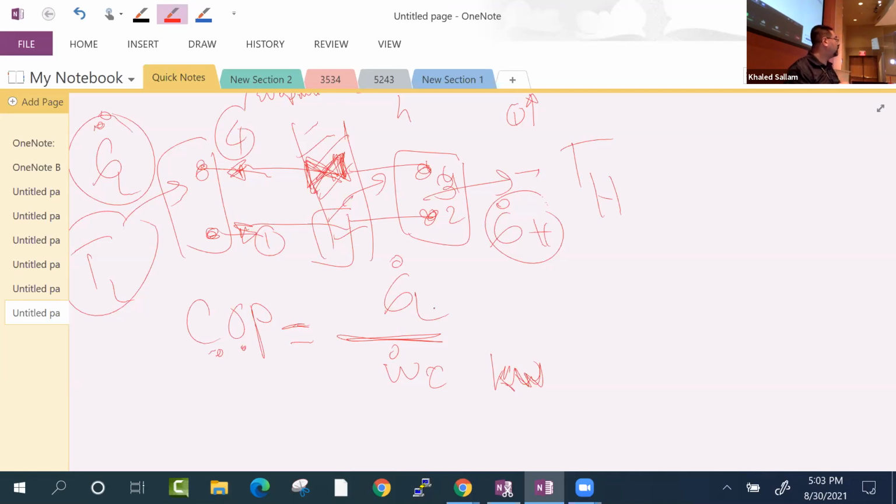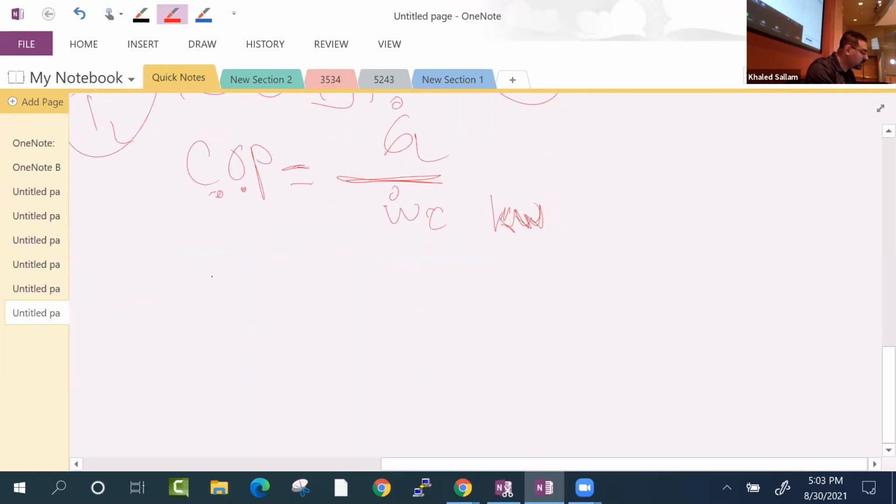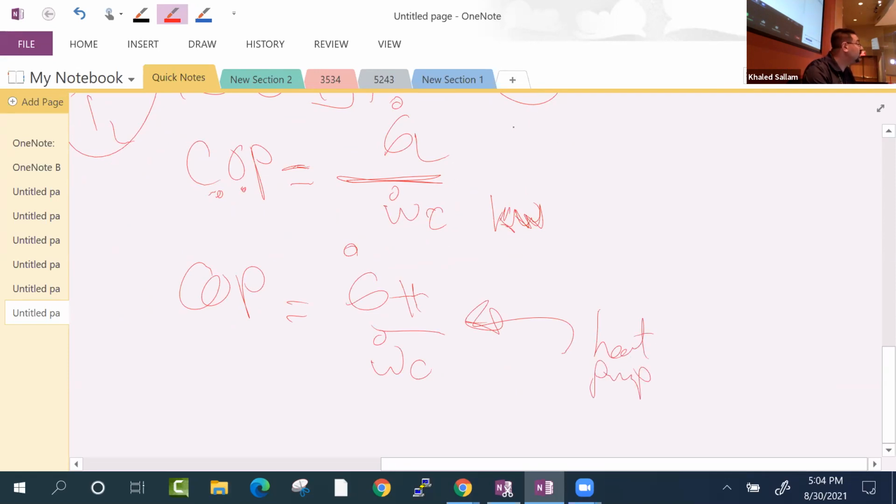So in that scenario, what do you care about? The Q dot H or Q dot L? Q dot H, that is your goal. So there is a COP that is Q dot H over work done by the compressor. So when you do this, that's called a heat pump. And when you do this, Q dot L, that is a refrigerator. Okay? So the same cycle can work as a refrigerator and can also work as a heat pump. As a matter of fact, our air conditioning at home is like this.